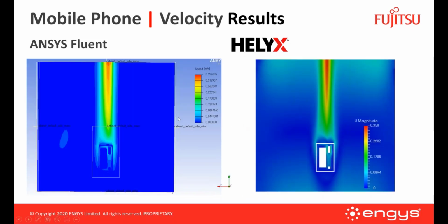Let's look at the velocity results. Again, we can see similar natural convection above this device, with a peak velocity in the middle of this buoyant flow right here. And we can see the speed, the max is 0.357. Here we're at 0.358. So it's nearly identical between these two cases.